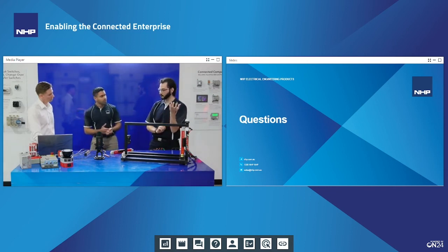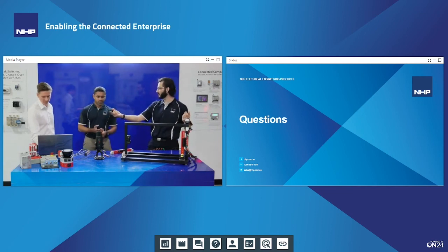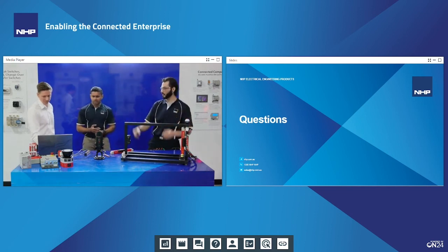So one device needs to be safety rated to generate the CIP safety packet, and then the other device needs to be able to decode that, and then send the response. That's all that really matters in a black channel.